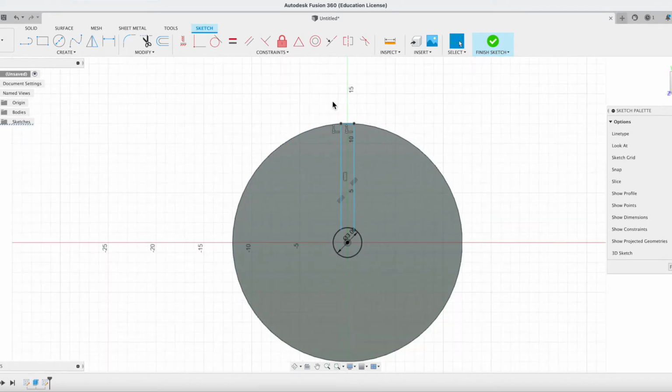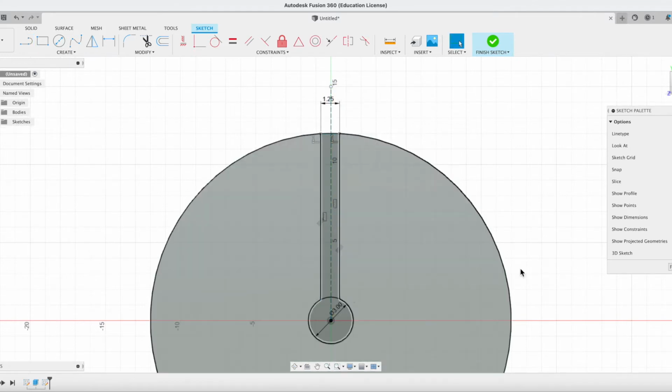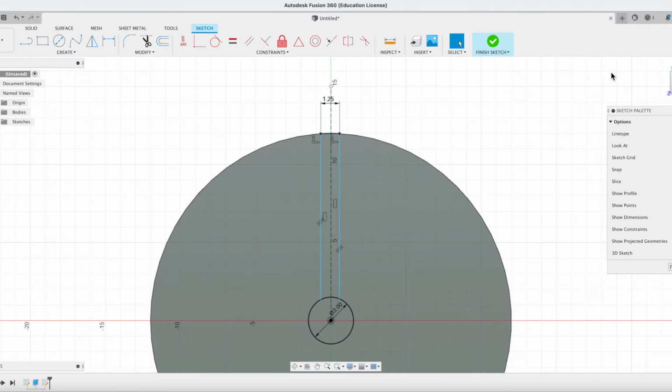Okay, now we're gonna do some minor dimensioning, per se. Oh, wait, actually 1.25 is what I want it to be at. And I'm going to draw a center line so we can have this fully dimensioned. This will be construction, and we all remember how to do construction lines. Click line, X, construction line.